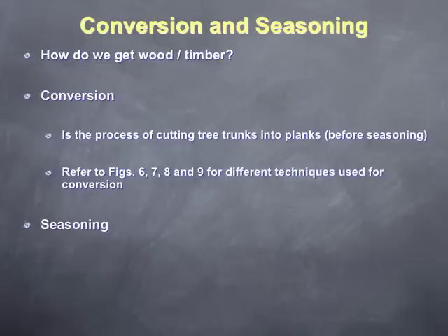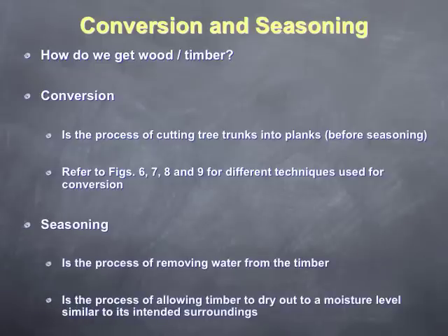First of all, conversion. This is the process of cutting tree trunks into planks before seasoning. And there are many different techniques used, as we shall see later. Seasoning is the process of removing water from the timber, and it's also a process of allowing timber to dry out to a moisture level similar to its intended surroundings.